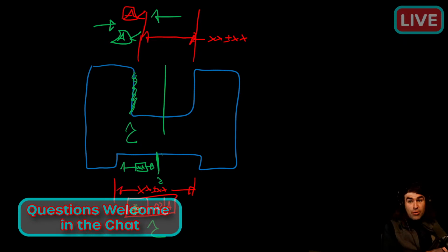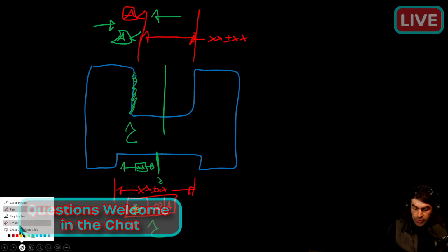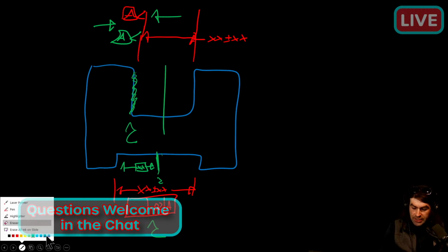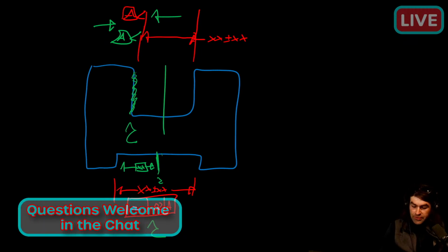Symmetry's been removed from the 2018 standard. As long as it's an option in CAD programs like SolidWorks, people are going to keep using it. For the uninitiated, it makes logical sense what it does, whereas position does not make sense. So if you've got a designer or an engineer, and they're not hip to GD&T yet, they're going to see that symmetry symbol and be like, oh yeah, that is the ticket for this situation. That's what I want to do.